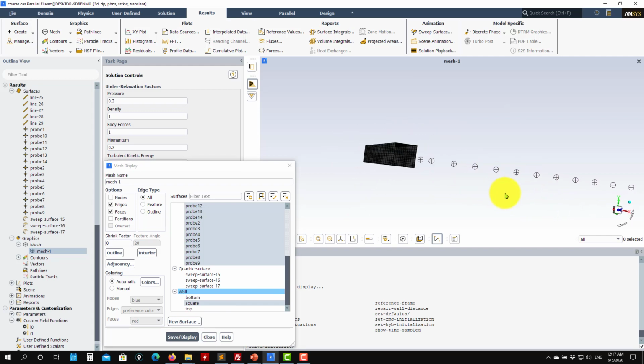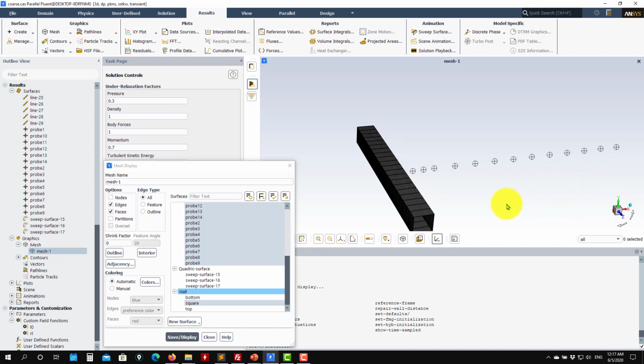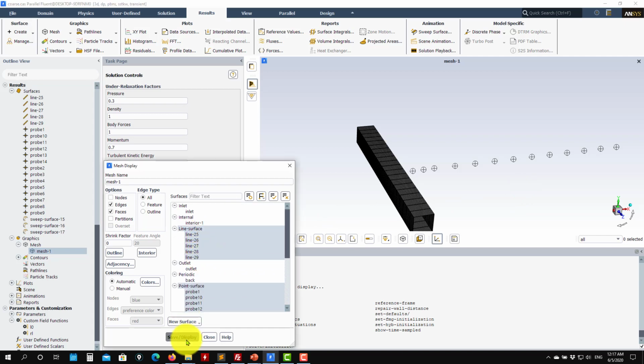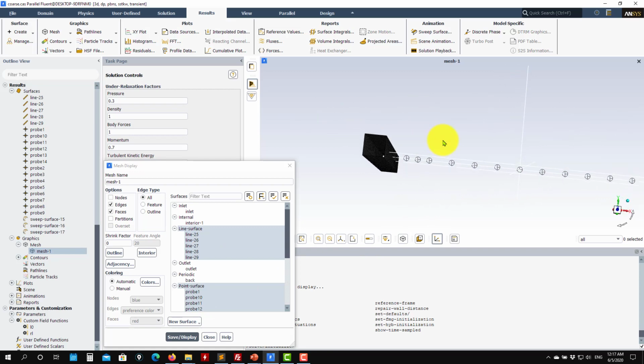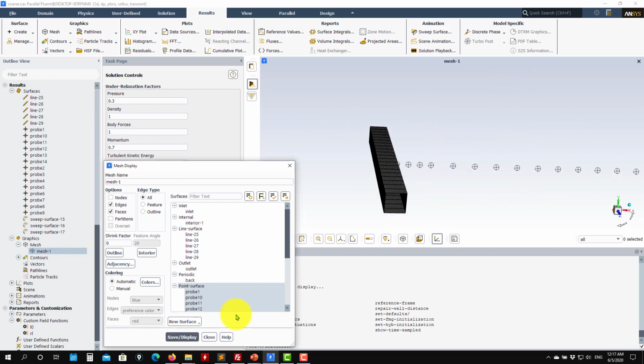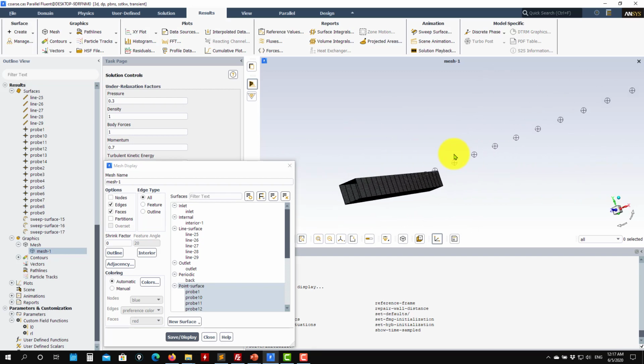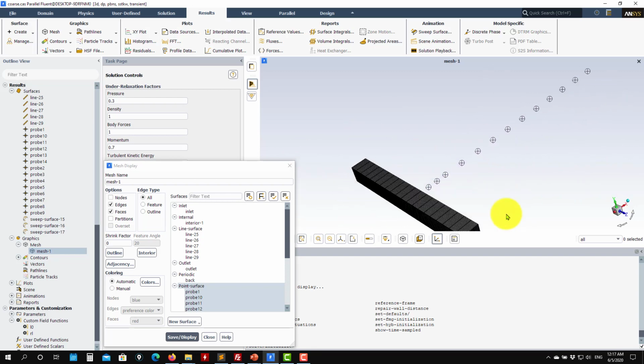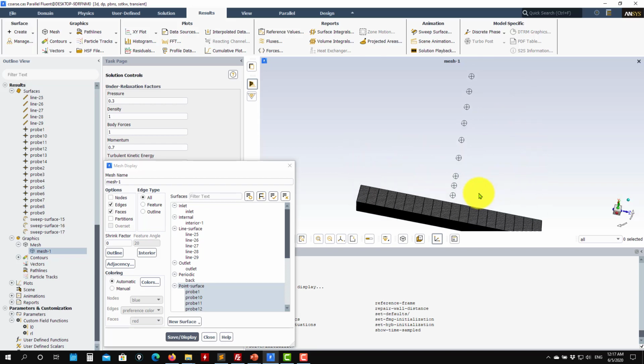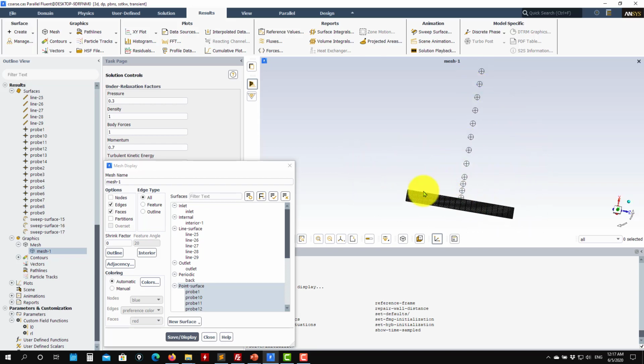In different points I want to sample velocity, pressure, or whatever, and then I can use that information to get my energy spectrum. There are also some lines that I put there where we can do some sampling. See that I put many lines there. This is the thing when you go unsteady and you're doing things the right way: before starting the simulation, you need to add all these points and start to sample the solution. It might also be a good idea to add points in other locations, in different regions, so you can do your sampling.